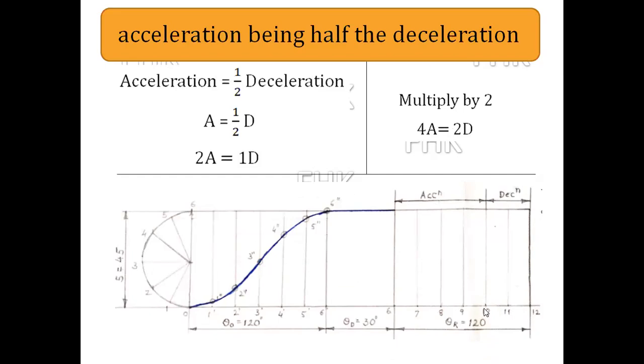And from that I will draw the vertical line, and that vertical line I will divide again into 6 equal parts. This vertical line, not this mid line. In the previous session, there was uniform acceleration and retardation, so a uniform length of outward slope was for acceleration and the same length for deceleration.